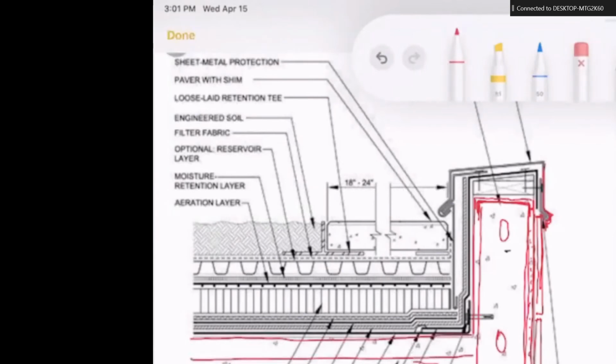And then on my Y flange, I may have my open web joist right here, and so on. So that will be my open web joist, resting on that Y flange. So decking, I do all the stuff they're doing here based on that system that they have, if I wanted to use it. But did you see how I replace the stuff that they have? Even if it's concrete, you can go ahead. This detail right here, nothing wrong with this stuff over here. I can literally use it, assuming I want to use this system.